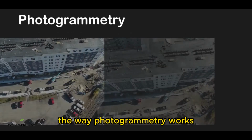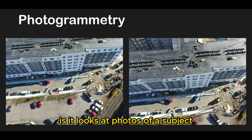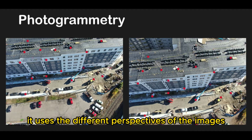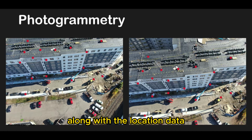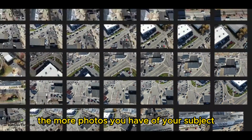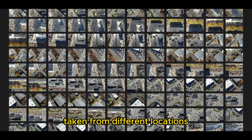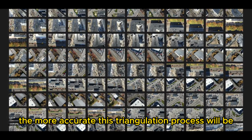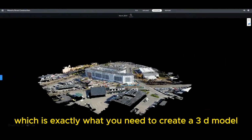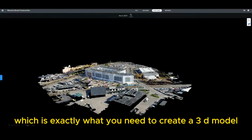The way photogrammetry works is it looks at photos of a subject taken from two or more locations. It uses the different perspectives of the images, along with the location data of where the images were taken, to triangulate the locations of points on the subject. The more photos you have of your subject taken from different locations, the more accurate this triangulation process will be. The result is accurate point locations plotted in 3D space, which is exactly what you need to create a 3D model.